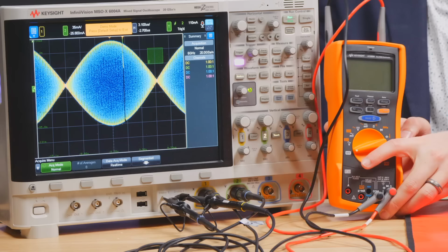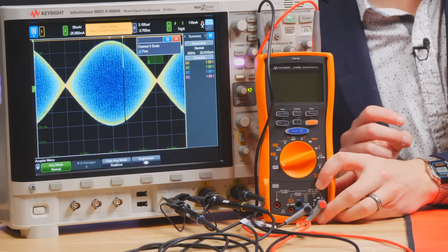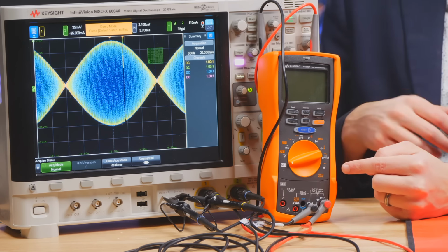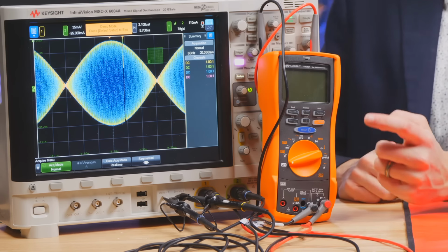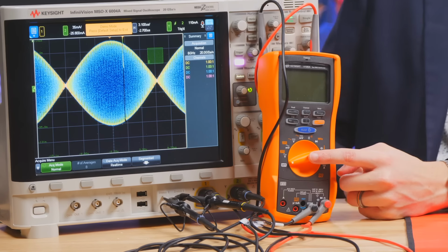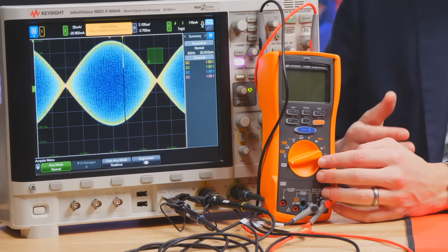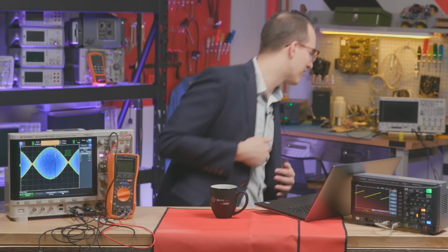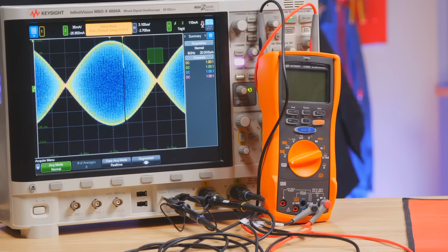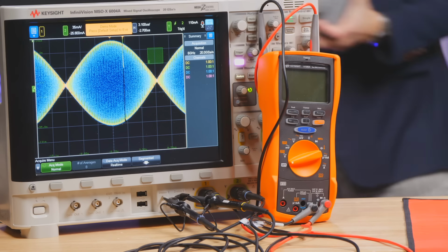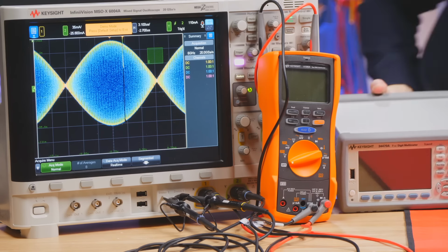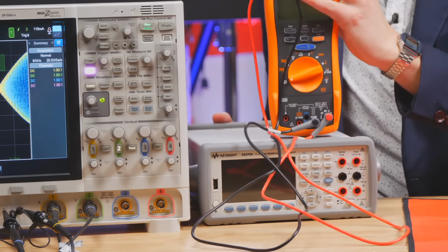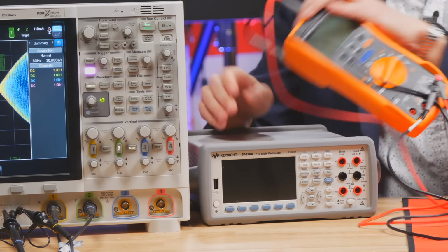I told my video guy I wasn't going to do a close-up on the DMM, but here we go anyway. So there's a ton of capabilities. You still can do a ton of different measurements on a DMM. That's why they call it a multimeter. The same is true of benchtop, but this is a 4.5 digit handheld DMM, and that's about as high of a resolution as you get on a DMM for a handheld option. The benchtop ones go up to 7.5 digits. If you have something like a 7.5 digit, you're able to get a lot higher resolution compared to a handheld DMM.